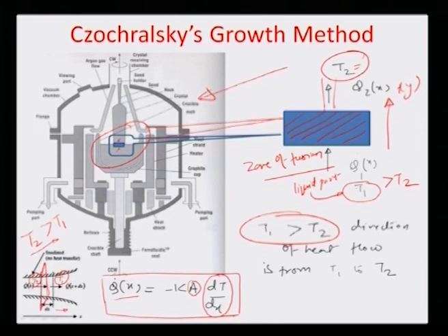Okay, so the heat flows from T1 towards T2, and we need to investigate how the rate of heat flow into the zone of fusion from the liquid side and the rate of flow out of the zone of fusion to the solid side would be balanced with each other. This heat loss is also a cause of the formation of the solid, which means that in a solid state, as you know, the bond energy is always higher, and therefore there is a heat of formation of the solid which is lost. It is called the latent heat of formation of the solid.